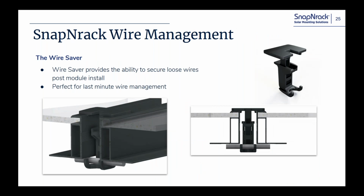We've also designed this little ratcheting device here. It's called the wire saver. It's a little plastic device that will pin a PV wire. As you see here, it pulls it tight up against the module. So if you've got a large array, you accidentally missed one of these wires and it's on the roof, you can get out there, use one of these, and it'll pull it tight up against the module frame, and it'll no longer be sagging on the roof.